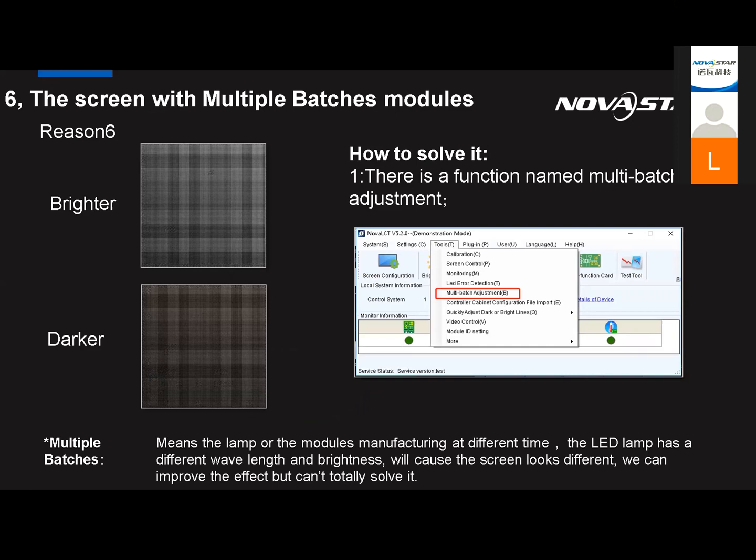The final reason, a screen with multiple batches of modules. For this problem, we have a tool in NovaLCT, multi-batch adjustment.